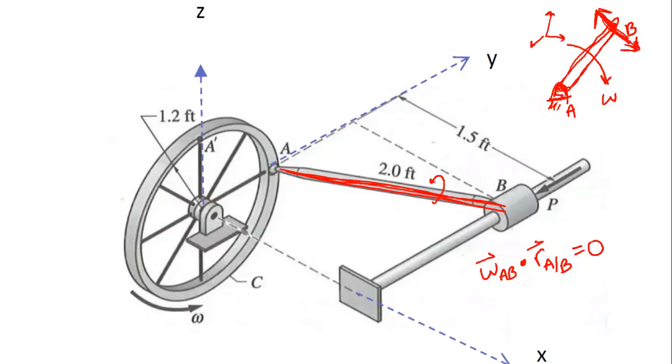Aren't R and omega? Well, I guess that was my point there. If the vector R and omega are parallel, then this thing would just be spinning, like what I did right here. It would be like taking your pencil and twirling it between your fingers, right? Essentially you're never going to have any displacement between A and B. So if they're parallel, you don't really have any motion. So they're absolutely not parallel.